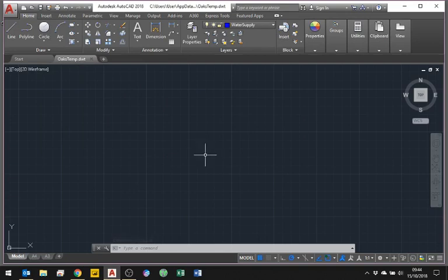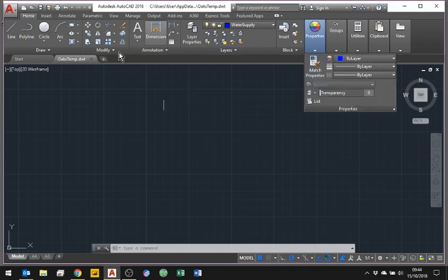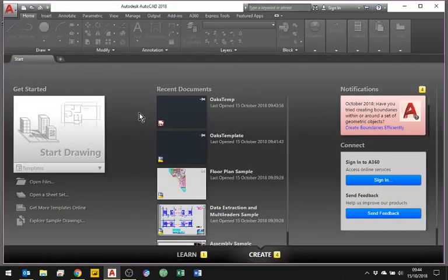The reason you might need relative paths in there is if you had used any external references or loaded any bitmap or raster files, you do need to know where they are. So if you are using them in your template, you need to make sure you have updated the relative paths. Okay, I'm now going to close that file down. Now you'll notice that I have two files here now. I have my AutoCAD Template, which is the DWG file, and I have the AutoCAD Temp, which is the DWT file. And you'll notice there are different paths to get there.